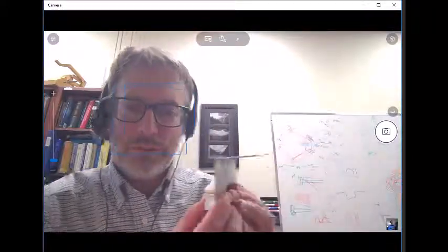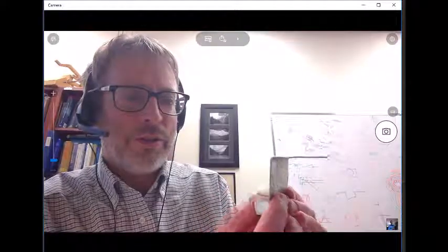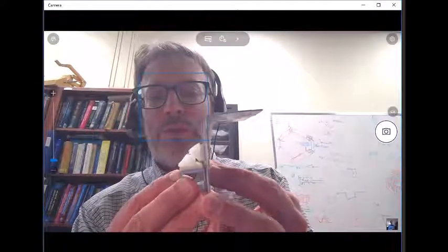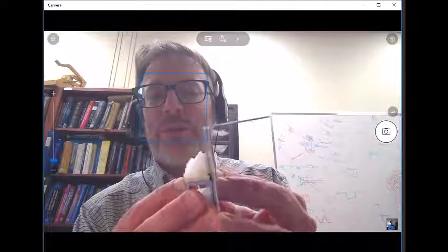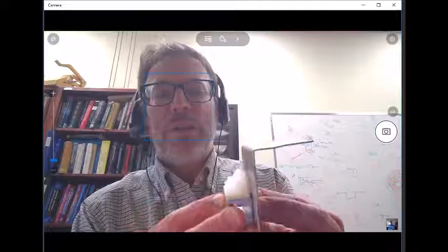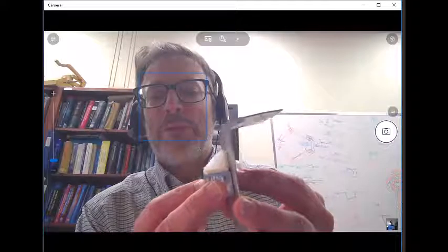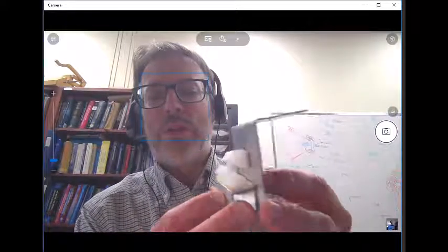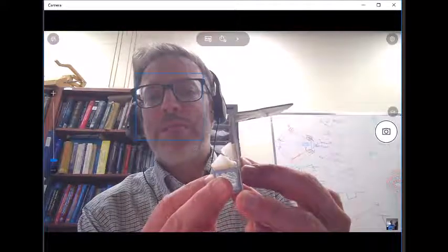So here's a little sort of depiction of a fillet weld to join two parts together. Okay, so I can see I got a right triangle there. Here I can see the throat dimension opening up. Okay, that's 0.707 times the sides of the triangle. There it is. So even if the weld is not in shear, but if there's basically a normal stress this way or a normal stress this way, we're going to do our design as if the weld failed along that throat dimension T.